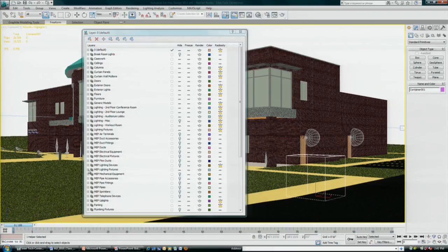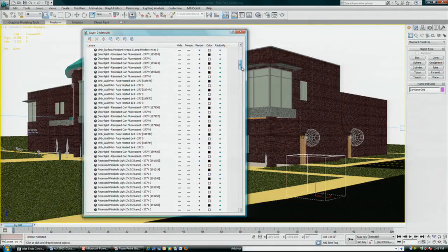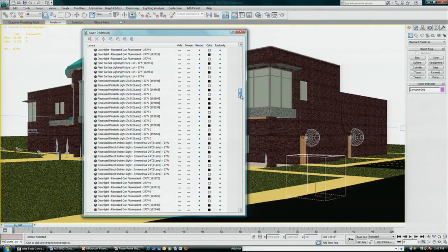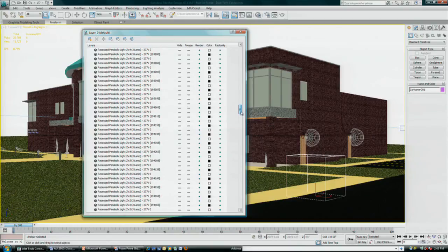And now, lighting fixtures, I'm sorry. All these lights right here you see in that subcategorized list have been offloaded because they're not necessary for the rendering. Just imagine what the render time is. If you figure lighting increases your render time exponentially, think about that 8 hours versus 9 minutes.